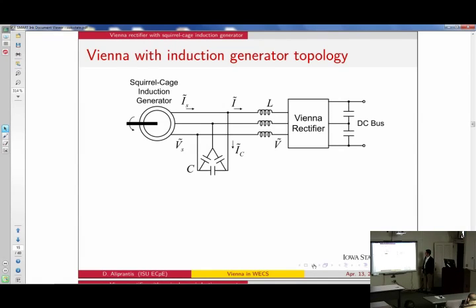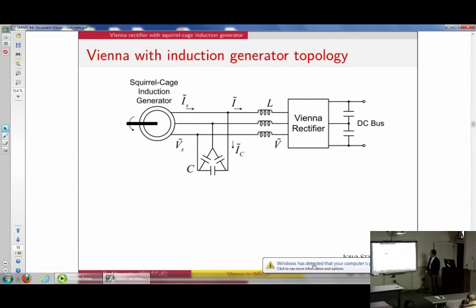Now, this induction generator, if you took the undergraduate course in electrical engineering, it turns out absorbs a lot of reactive power. That means that if you just connected this induction generator, it would not work, because you would be violating that angle constraint that I was talking about previously. That beta, or the difference between the voltage and the current, would be much more than 30 degrees.